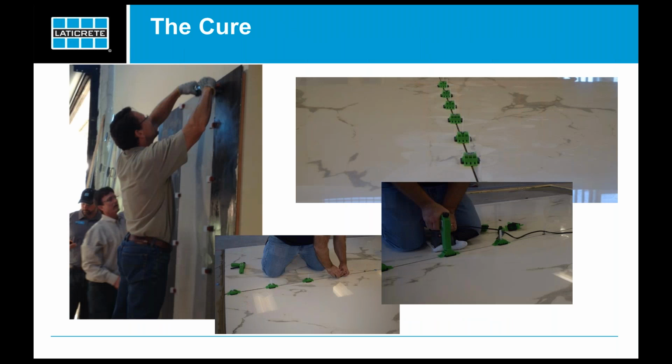Here again, you see the strapping systems that are used both vertically and horizontally. And as you're doing this, we really also want to start thinking about cure rates now. How long should these floors or these walls cure before you start exposing them to traffic? The general consensus in this regard is to wait at least 72 hours if you're going to start putting cart traffic or heavy loads on these floors. That's a good rule of thumb.